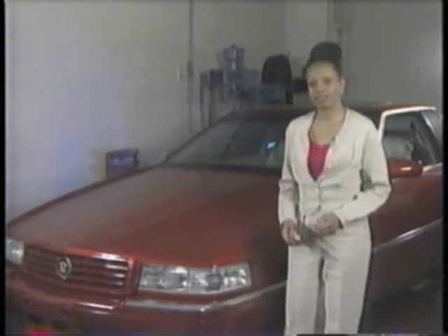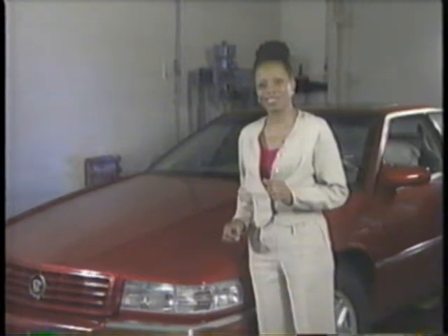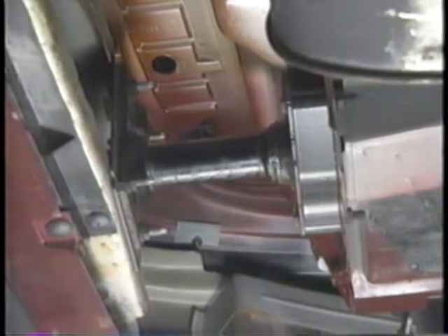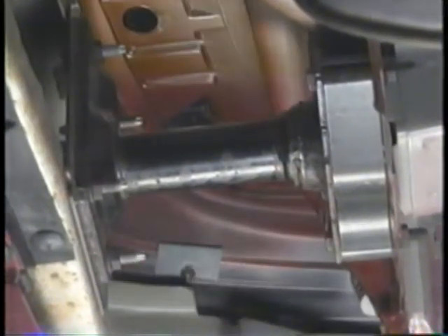In low-speed accidents, the car's bumpers take the brunt of the impact. Let's take a look at their design to see just how the bumpers cushion the impact. The bumper assemblies of modern vehicles are designed to absorb the energy in a low-speed impact. This is done by constructing the bumper assemblies out of an energy-absorbing foam that is stiff but will deform upon impact. Other vehicles have used energy-absorbing hydraulic cylinders similar to shock absorbers, mounted between the vehicle chassis and the bumper.